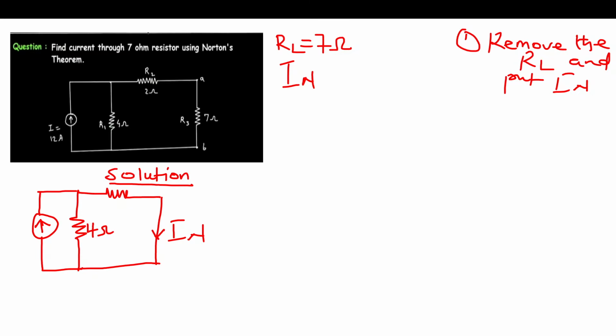I hope you all get it. So this time around, I'm not going to draw my resistor, the 7 ohm resistor there. I'm going to replace it with IN. Okay, that is the very first step. And then we solve for IN.